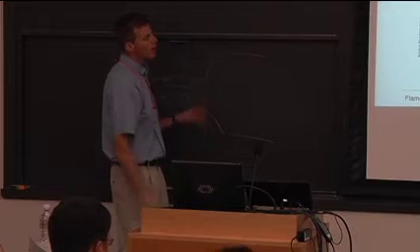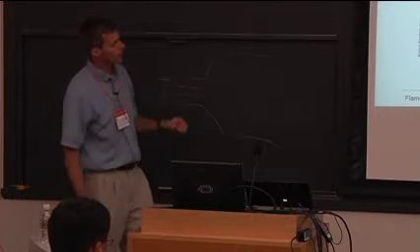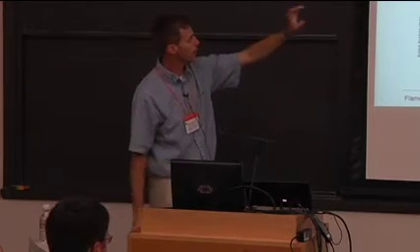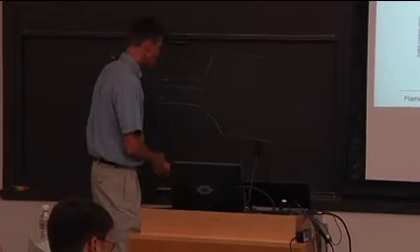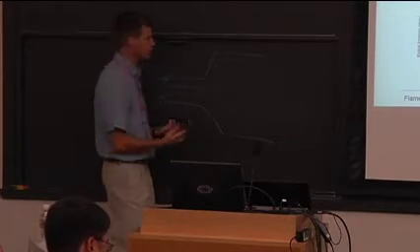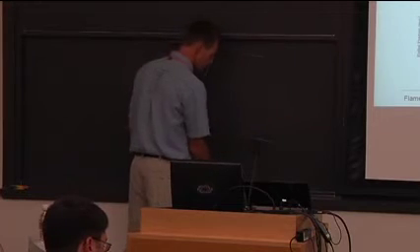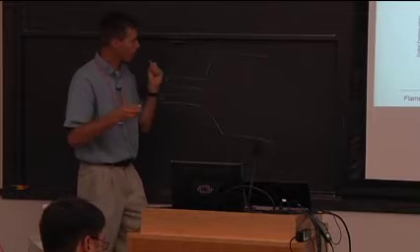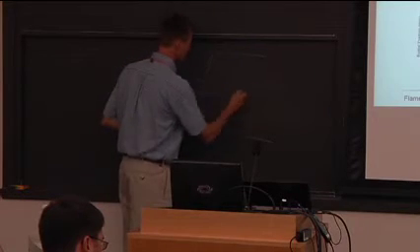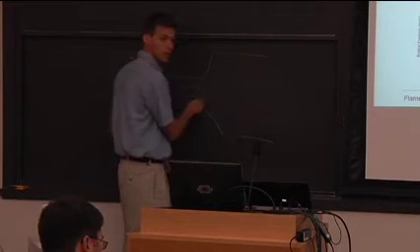All right? What happens, though, is as I increase flow velocity, I march from top left to top right to bottom left to bottom right. What happens is, above some critical equivalence ratio, I get a bifurcation. And if you're watching this flame and you're increasing the equivalence ratio ever so slightly, all of a sudden, bang, the flame pops back. It sits in this inner shear layer.